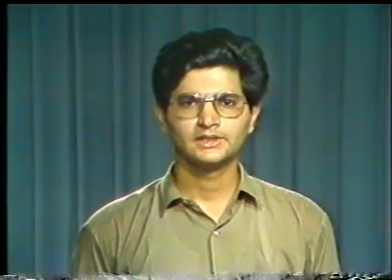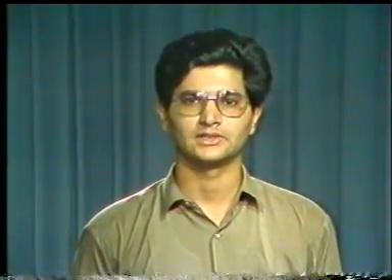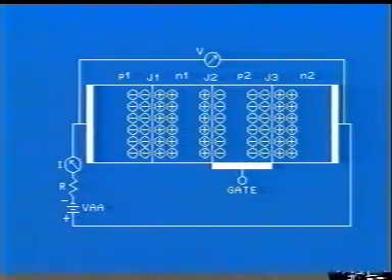So far, we have kept the anode positive with respect to the cathode. What would happen if the anode is made negative with respect to the cathode? We'll first make a qualitative analysis of the behavior of the SCR in the reverse bias region on the basis of the structure of the SCR. Application of reverse bias has caused the junctions J1 and J3 to be reverse biased and junction J2 to be forward biased. Therefore, depletion layers at J1 and J3 have become wider.